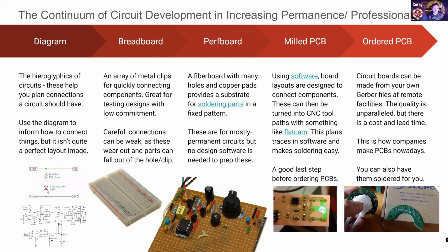On the left is the diagram. And for me, a circuit diagram is like a plan for how you're going to build it. It's very much a blueprint where you're thinking about the connections that you have. It may not be exactly how you lay things out in physical reality, like where they're located next to each other, but it's going to point out the connections that you want to have. I've got this one that was animated earlier, and then a bigger one. This is for a radio down here. But circuit diagrams like that help you diagnose the logic of what you're doing. And they can be really helpful for showing this needs to be connected to that, and this needs to connect to there, without being where you plug it into the breadboard.